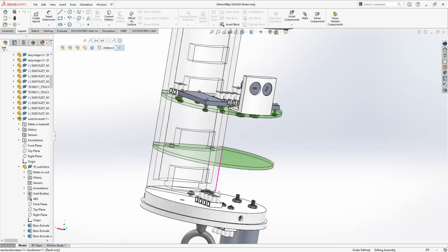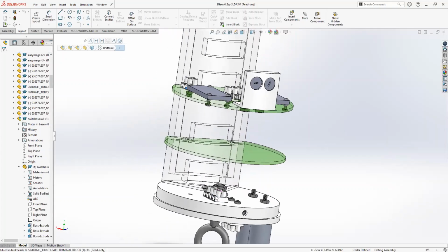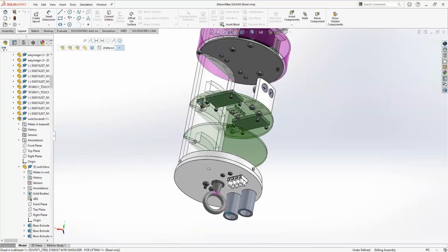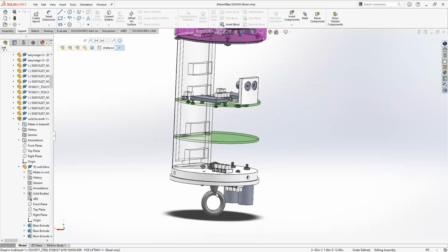So yeah, those come down to here, and all the other electronics that we have would be coming down to here. All the other ejection charge type stuff would be coming down to here. And then it'll have little holes that are airproof so that no ejection charge gas could get into your avionics bay, because that'll absolutely destroy the electronics. And also